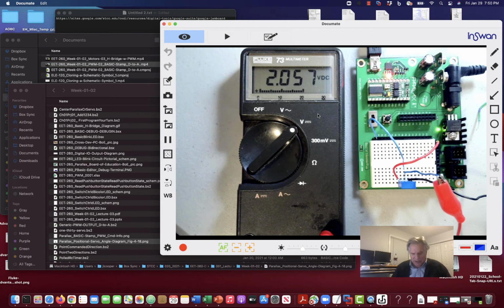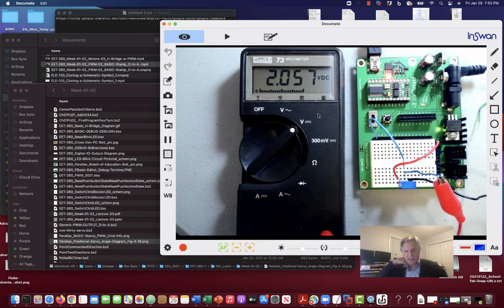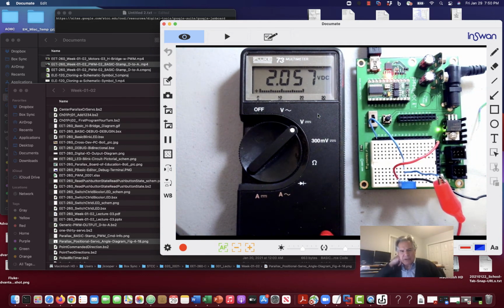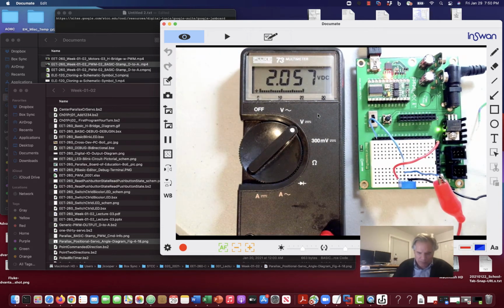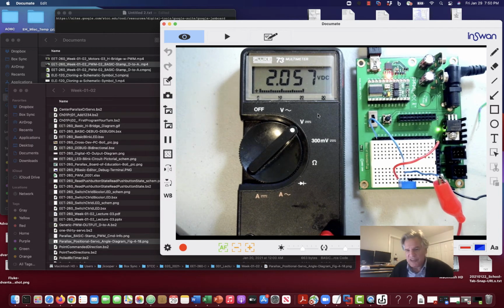In our example, we needed to do some more filtering, but you got the idea. You could see the voltmeter sort of averaged things out and gave us an accurate reading, and if we had more filtering, our oscilloscope display would have floated up with a smoother looking DC level than that kind of shark fin charge discharge waveform that we had. But you could see the DC level,